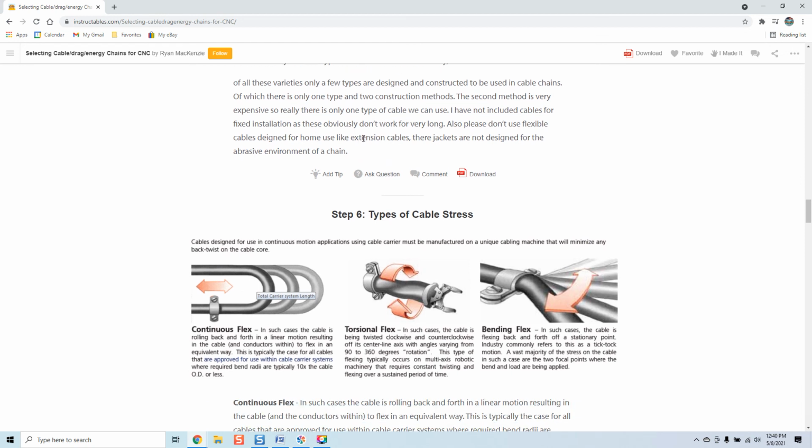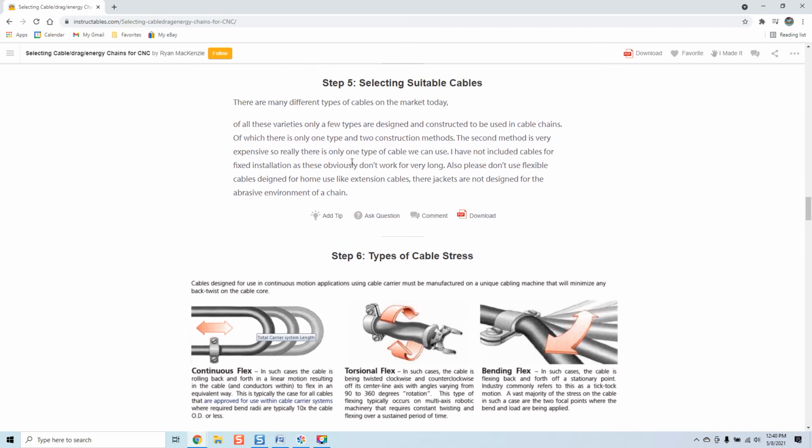Now, that's interesting that he said this, because some of this I agree with and some of this I disagree with. And I disagree like many of you do, because we realize that cables over time are all going to degrade. They are consumable items. In any capacity, a cable in engineering is considered a consumable. It will eventually fail in one capacity or another. Either it's overflexed, or the terminals aren't holding up, something may give. But in a robotics use, it usually happens at a more accelerated pace because we're dealing with motion.